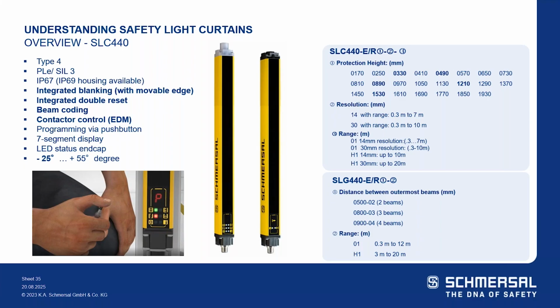So some great availability of different resolutions, different ranges, different protected heights to meet almost every single application that's out there. And they're like grids, again, your 2, 3, 4 beams. Upwards of 12 meters range, and then the high range goes upwards of 20 meters on the 440 series.